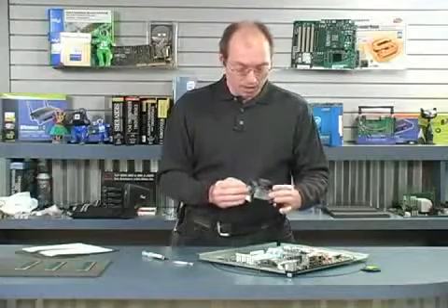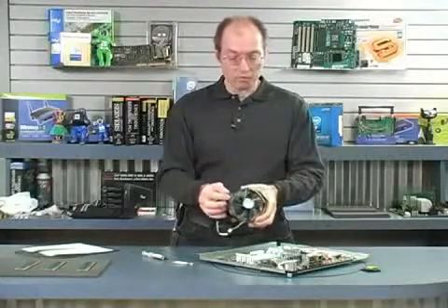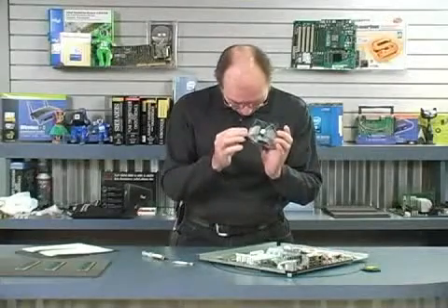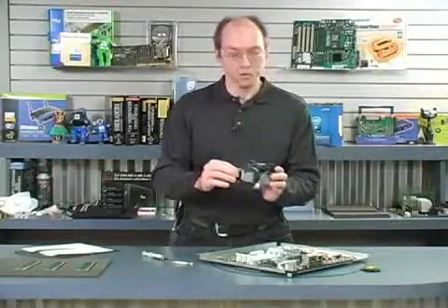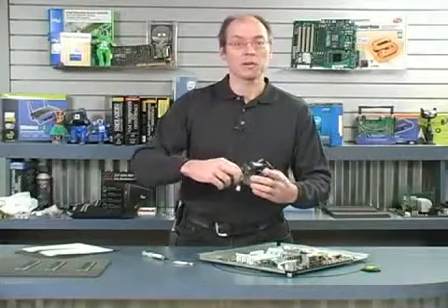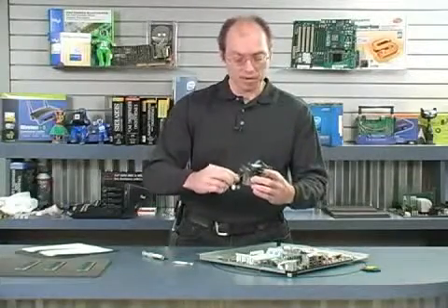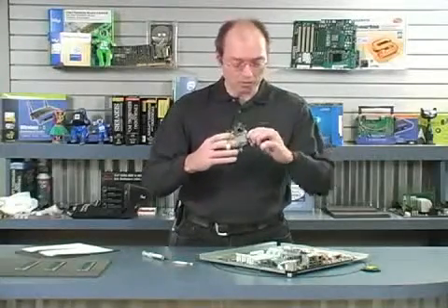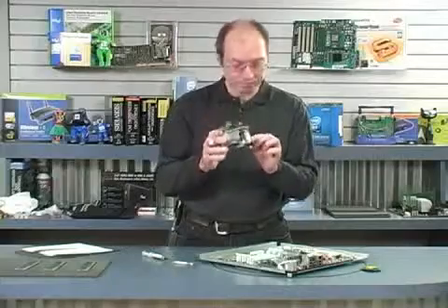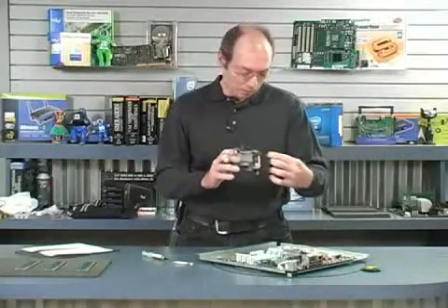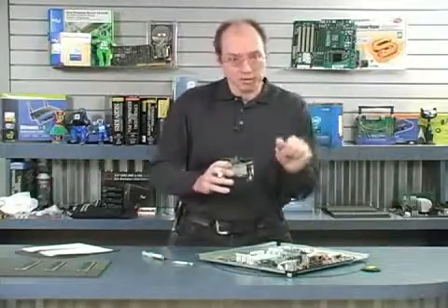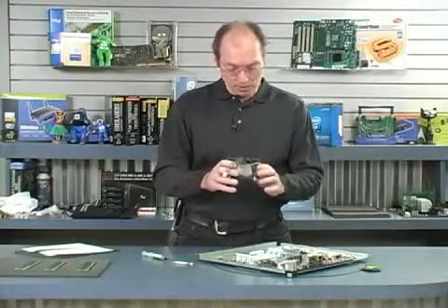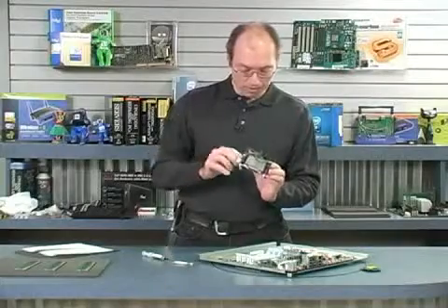Intel heat sinks are noted by these 4 push-pin retainers, and they have arrows on them. What's kind of funny is that when you install the heat sink, the knobs on top of these retainers have to be turned the opposite way of the arrow. So I'm making sure that all those are turned in the right direction. It's a common mistake that people see the arrow and think they have to turn it that way. That's actually for the removal of the heat sink. So make sure these are all with the proper orientation.